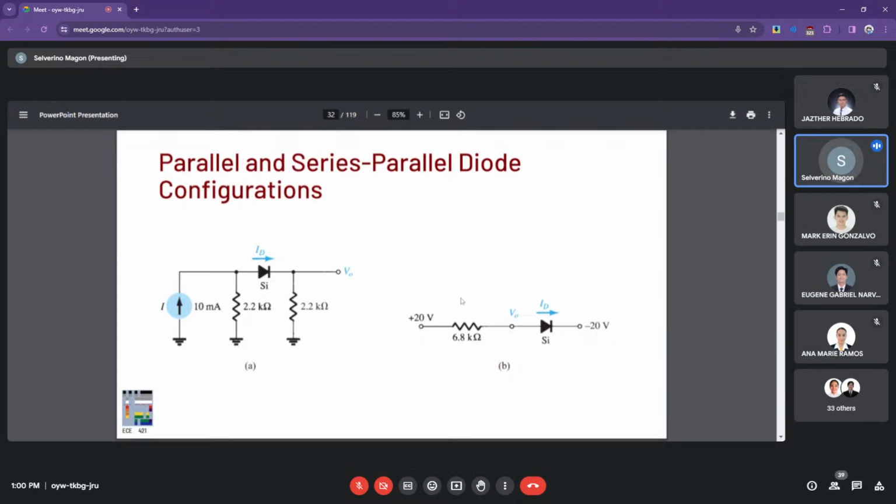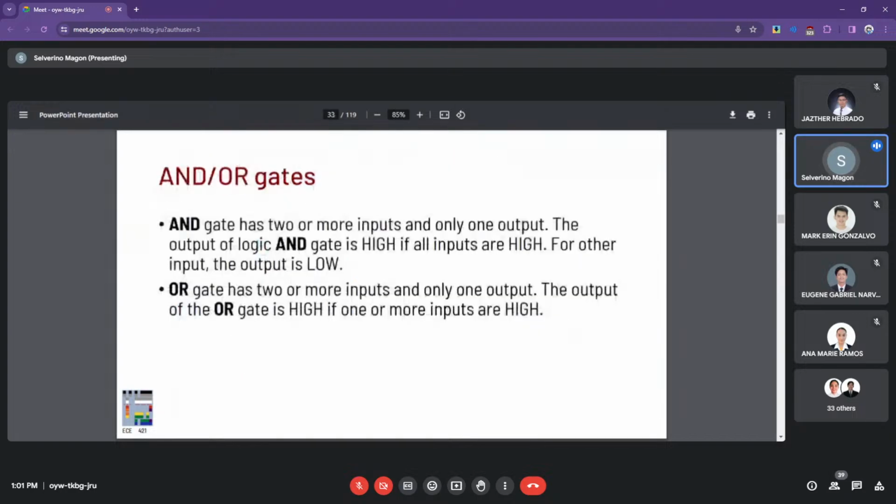And if you have a 40 volts supply across the loop, then you just subtract the 0.7 drop from the silicon, and through Ohm's law, you can come up with the value of the current based on the value of the resistor in series right there. So that's the current ID. Again, I'll come up with the calculation for this. It's not directly available, I think, in the handbook, but I'll share the examples for that next time.